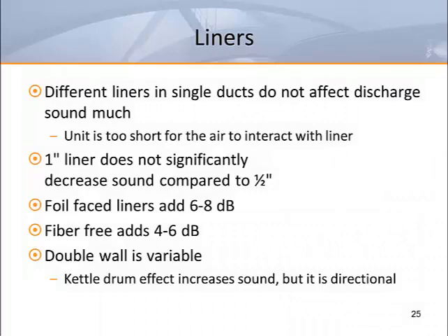There are some general rules regarding the effects of liners on terminal unit acoustics. In a standard single duct terminal, the choice of liner has little or no effect on discharge sound because the units are short and the airstream doesn't really contact the liner. The softer the surface of the liner is, the more absorptive it'll be. This tends to create lower discharge sound levels. The harder the surface of a liner is, the less absorptive it'll be.